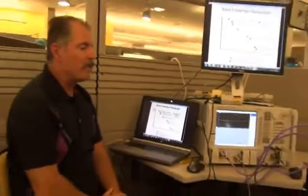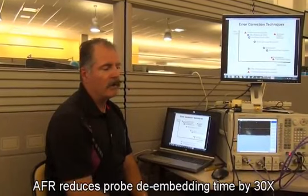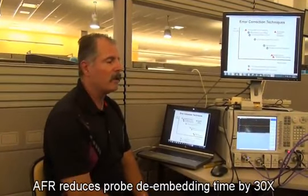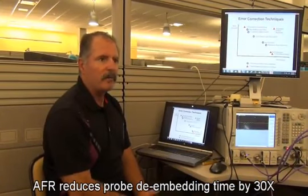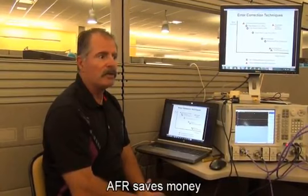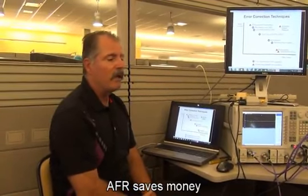And so there are many different ways to skin a cat. The way that we're going to do it today with AFR is going to probably save on the order of 30 times the amount of time spent. A TRL calibration kit, once you design it, fabricate it, use it, it's going to cost, who knows, $5,000 to $10,000, and the measurement will take maybe a couple hours.